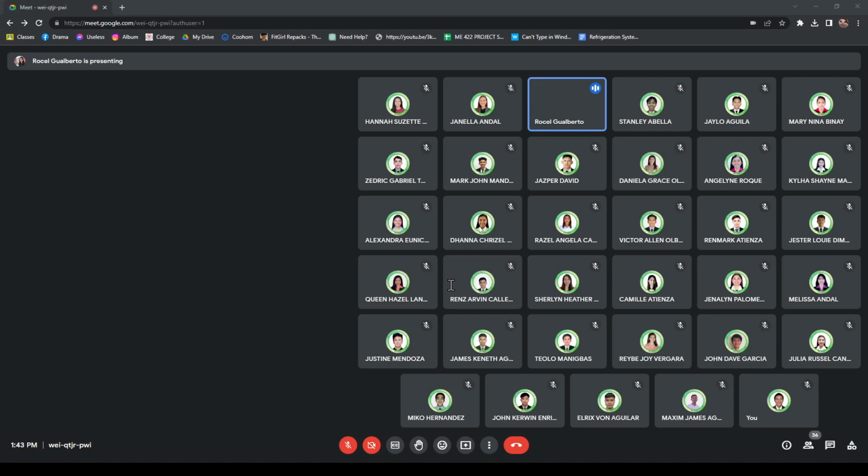Correction po, pakipalitan lang po ito. This should be sigma and then subscript L. Okay? Ulit, palitan po. It should be sigma and then subscript should be L. Okay? Yung isa would be sigma T sub I. Okay? Hoop stress on the inner fiber. And this one is hoop stress on the outer fiber. Okay? So you look at those equations, it involves the following components. You have P_I, R_I, R_O, P_O, and R_O. Okay? P_I is inside pressure. Okay?